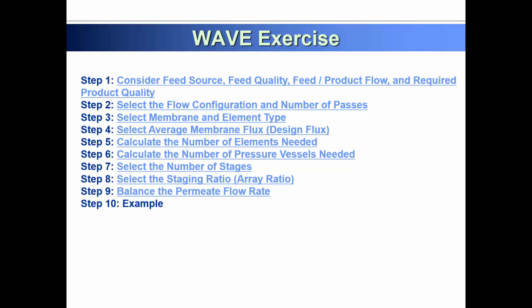So we will see how we can balance the water flow depending on recovery, permeate flow, and retentate. We make sure everything is flowing very smoothly, rather than having too much permeate flow and not enough feed flow, which leads to a lot of fouling issues. So this is all related to your optimized operating conditions, which can save costs and also protect your membrane from fouling.